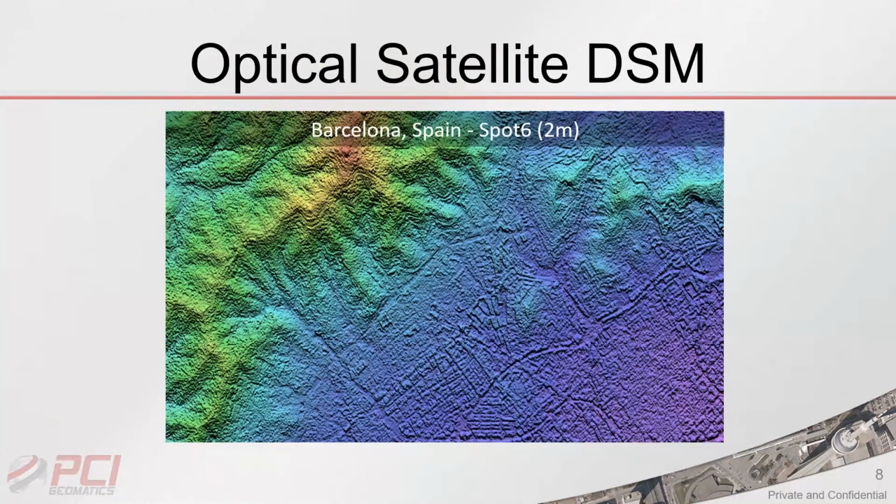Now the input imagery for that aerial-based DSM is of higher resolution. I believe the input resolution was 15 centimeters. In this case, we're working with SPOT 6 data.